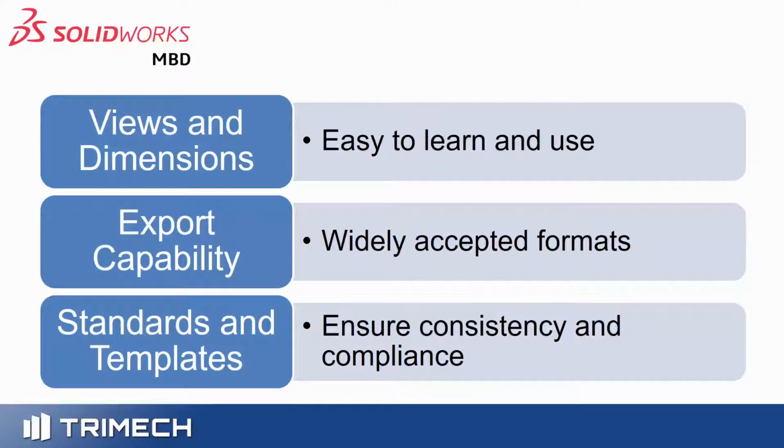So we just took a look at how views and dimensions are created and how easily you can create DimExpert dimensions directly on your 3D models. Then we took a look at some of the export capabilities and the kind of content that you can publish downstream for use on the manufacturing side. We also took a look at the standards and templates and how you can develop a quick little industry standard template for yourself. So that's been a quick overview of MBD.